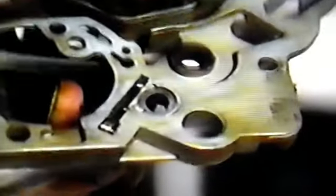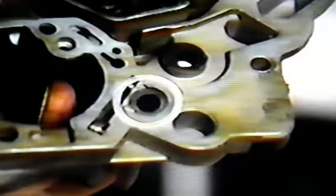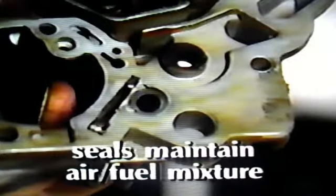The next step is to look at the air horn and inspect 2 seals. In most cases, you'll be able to reuse the seals, but if they do need replacement, you'll find new ones in the carb kit. They also must be replaced if the carb is soaked in carburetor cleaner. The function of these plugs is to keep atmospheric air out of the carburetor. One seal is at the accelerator pump plunger entry, and the other seal is for the green TPS plunger, which was taken out earlier. Both seals are extremely important for maintaining a proper air-fuel mixture, and here's why.